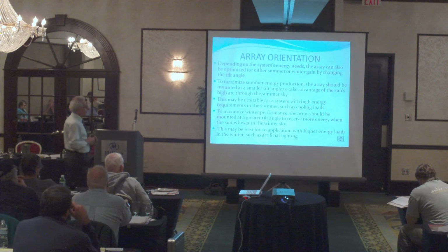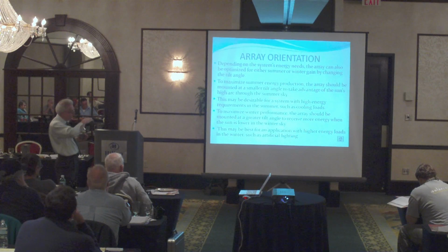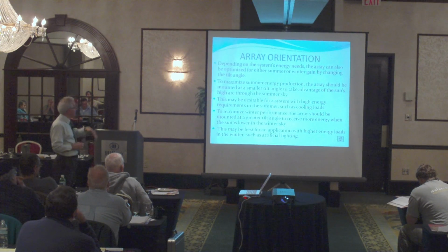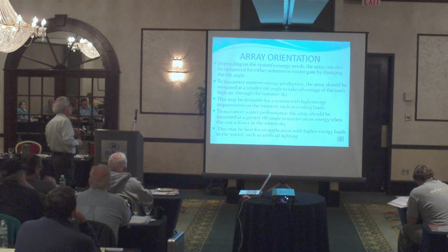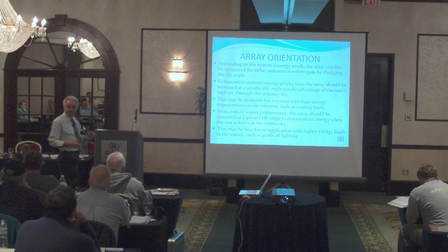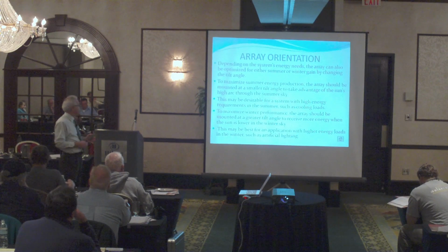Sometimes, to maximize the summer energy production, the array should be mounted at a smaller tilt angle, to take advantage of the high arc of the sun through the summer sky. That's probably good in the summer if you have systems for cooling loads.